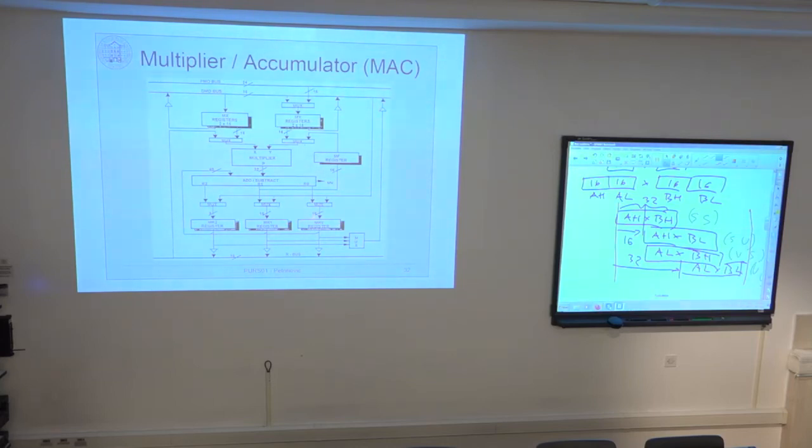For example, if I want to write some initial value to MR2, MR1, or MR0, then I use this mux to write the desired initial value. Here, it also has this feedback. So, for example, I can write to the MX register, but also I can take the value back to memory. So that is the purpose of this feedback loop.